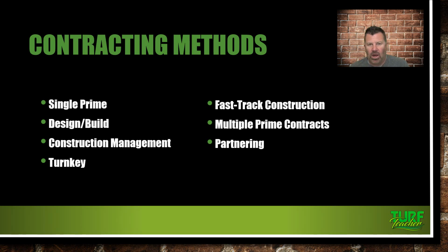Contracting method, single prime. Most of the time, that's what the true term general contracting is. They sub out everything and they are the single prime contractor. We did do the student union at UNCG where there were multiple prime contracts. There was the prime contract for the GC that did the building. Then there was a prime contract for the HVAC contractor and the electrical contractor, just because the amounts were so big that the state wanted them divided out into multiple prime contracts.